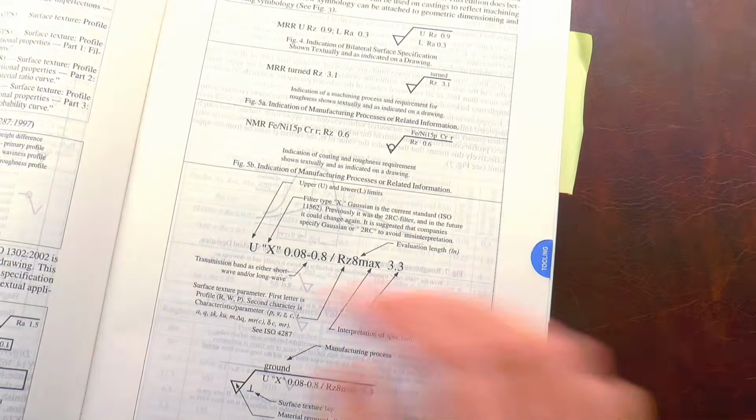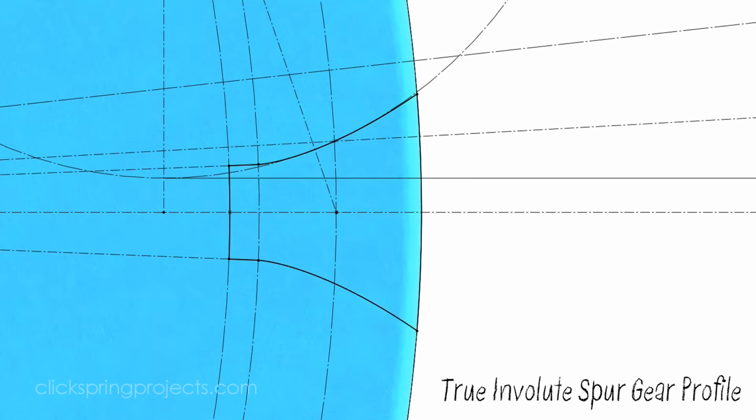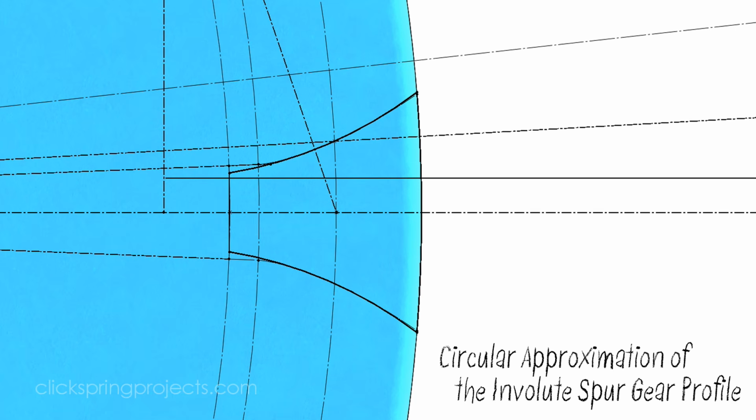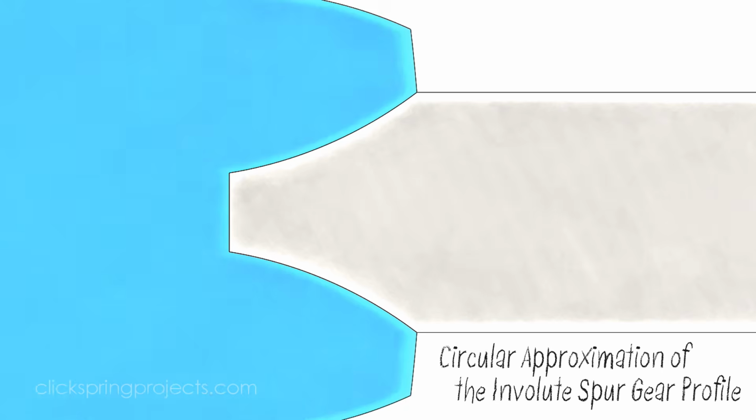Okay, so what about the involute profile? Well, things aren't quite so accommodating in this regard. There's no convenient radii written directly into the standard. But what if we applied the radius approximation anyway? It's not a huge deviation from the involute profile at any given tooth count. And it compares favourably to the error that we already accept from a set of commercial cutters at the end of each cutter range. So again, providing we're happy to accept this small compromise, we see the involute profile can also be simplified with radii. And so generating this profile also falls within the capabilities of the home shop.